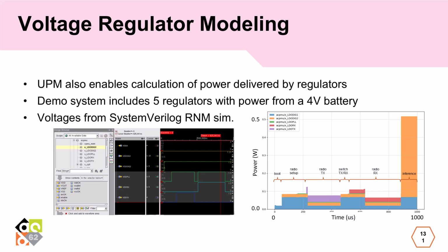And I mentioned we're sequencing the power by turning off supplies to blocks that aren't in use. In this waveform diagram, you can see that the PLL is on for receive and transmit, where the receive is only on for receive and the transmit power is only on for transmit. Since the simulation produces actual voltages on real-valued power nets, we can use those voltages in the 2416 model using the new 2416 syntax.